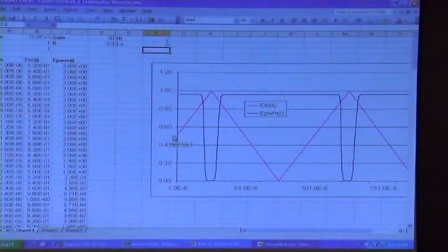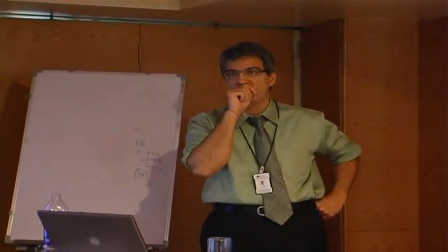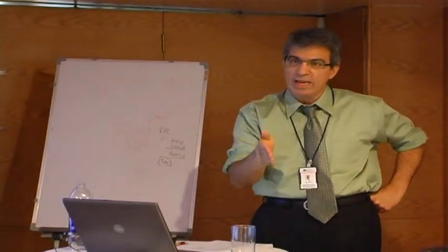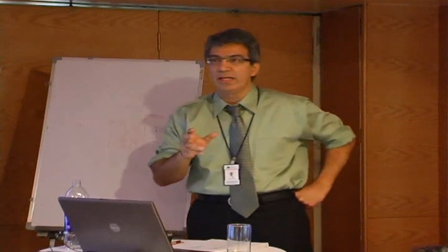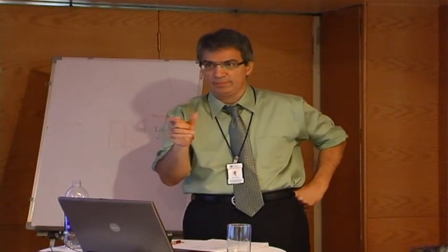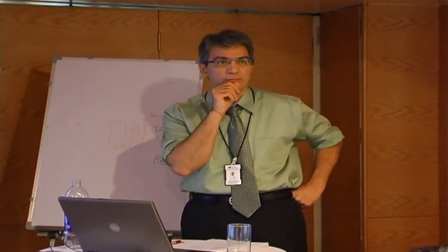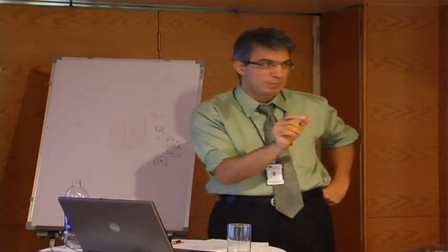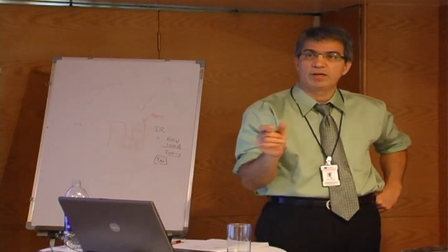Now, the only issue with this is that if your PWM frequency, let's say, is 20 kilohertz, 50 microseconds, then your simulation time step, we clamp it to be, let's say, 1/10 of the switching period. So if it's 50 microseconds, then my maximum time step in simulation should not exceed 5 microseconds.